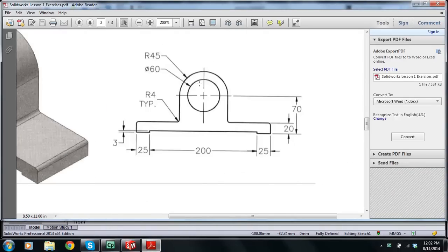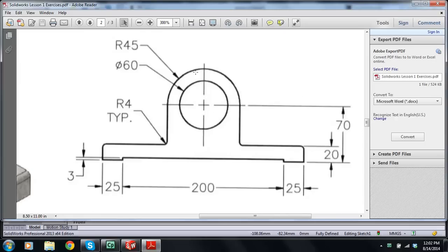Okay, we're on sketch number 4. So I'm going to take this a little bit slowly and just kind of go over a lot of the stuff that I've kind of introduced. So what are we doing? We're drawing 2 circles. It looks like a grandfather clock kind of shape, and the only thing that's new is we have these little curves here, and 4 little curves. These are called fillets. They're little curves. You see them an awful lot in engineering.